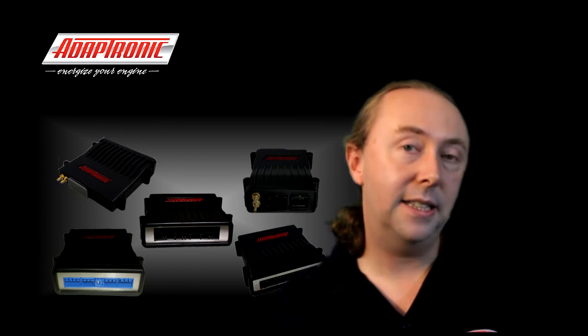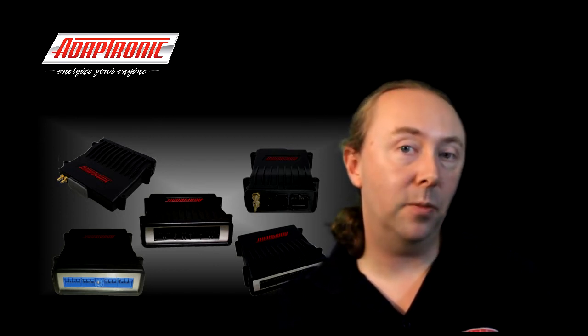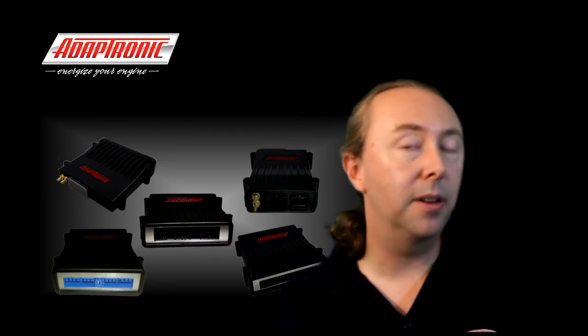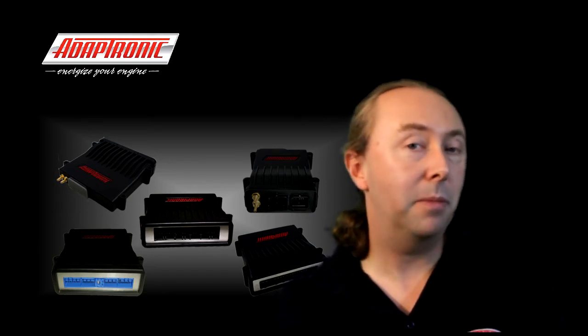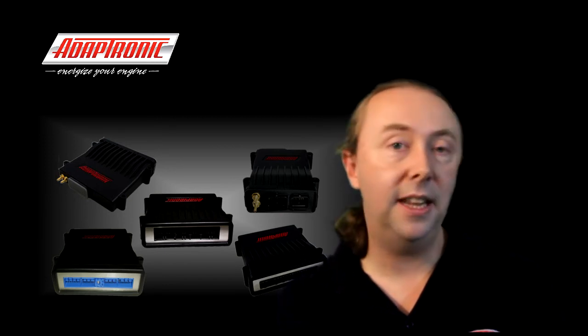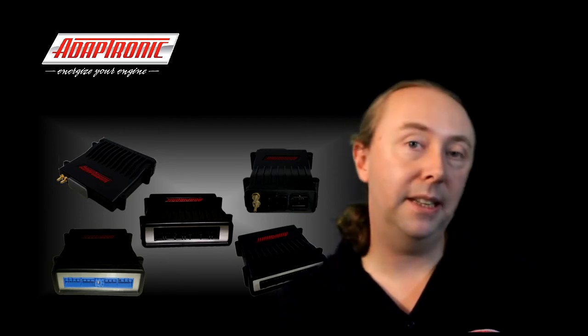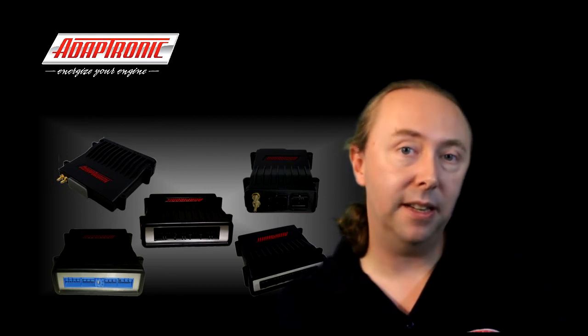Now the only other thing that I'd say about the post-crank idle tuning is that sometimes the engine doesn't want to idle up, and you put bigger numbers there and it doesn't seem to flare up the way it should. Then it's actually not because of an idle setting problem. It might be because the engine's either overfueled, because you've got too much cranking fuel in there, or it's underfueled and it needs more post-crank enrichment. So in this case I'd say try 10% more or 10% less in the post-crank enrichment map and see what makes it happier, and that'll help you stabilise on a condition.